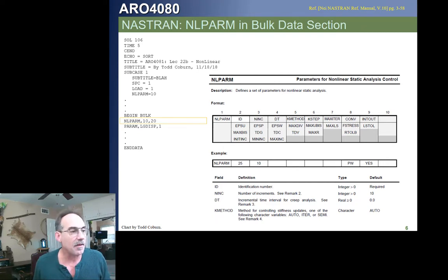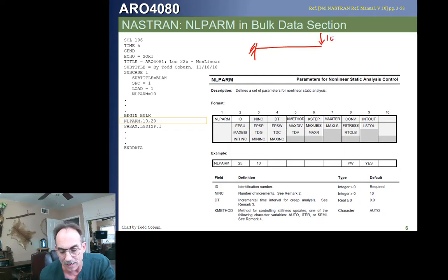our basic theory for doing analysis was assuming small displacements. We're really not going to change that when we're doing a nonlinear analysis, but what we're going to do, let's go back to that cantilever beam example. Let's say we have a load of 1,000 pounds that ended up giving us what we consider a large displacement. What this is going to do is we're going to take that load and we're going to divide it up.